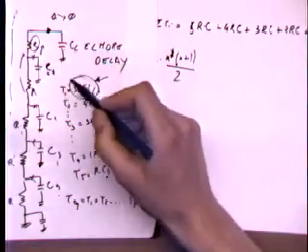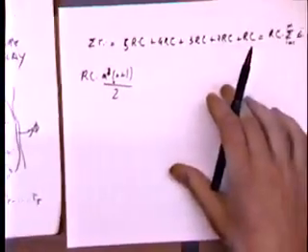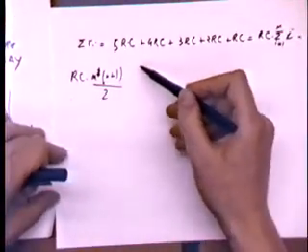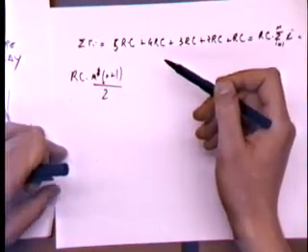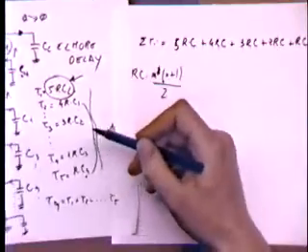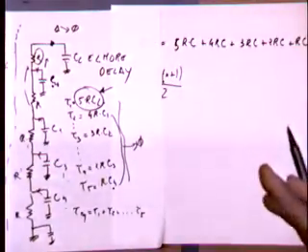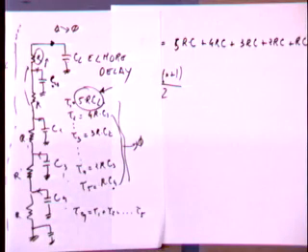If CL and all the parasitics were of the same value, you will get this analysis, and this will be quadratic in the number of inputs. In reality, the C1, C2, C3, C4 are not 0, but they're not as big as CL, okay? So you don't get linear, you get more than linear, but you get less than quadratic. You get something in between. It depends on the specific technology, okay? So let's go back to the slide.